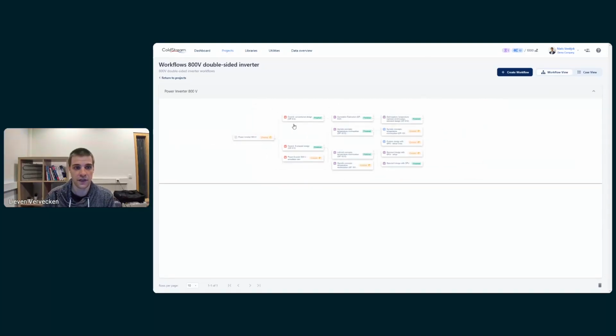We of course start with some regular CFD simulations to make sure that everything is set up correctly and that it makes sense. We'll then do the concept generation, try a bunch of different things, pins, materials, shapes, manufacturing settings, to then narrow down to one or two designs that are promising to further improve, to maximize the performance out of.